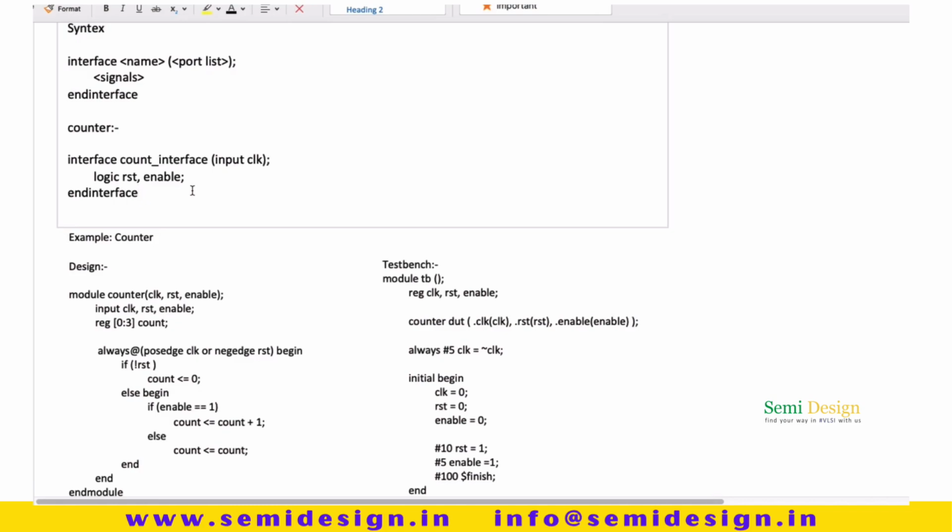In Verilog, we used wire and reg, which have a constraint of being usable in only one kind of block, not both, and they have only two values, 0 and 1. Logic can be used in both procedural blocks and assignment blocks, and it can have a 4-state value. So in general we always use logic when dealing with an interface. This is the basic, simple syntax for an interface.